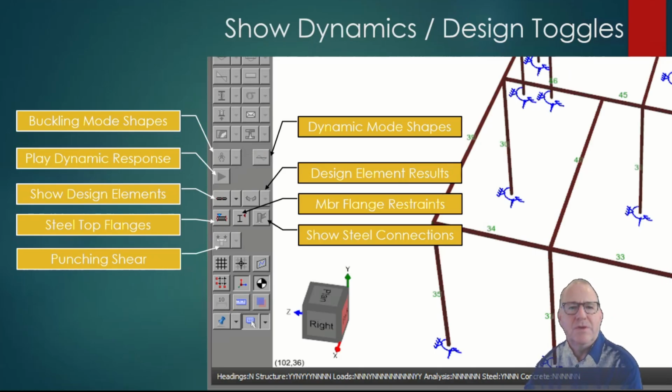Okay, moving on. If you're looking at the design tools and the dynamics, if you've done a buckling analysis, this tool comes alive and you can show the buckling mode shapes. If you've done a dynamic analysis, this will allow you to show the mode shapes too. And it's fancy enough to say you can do a dynamic response animation in effect.